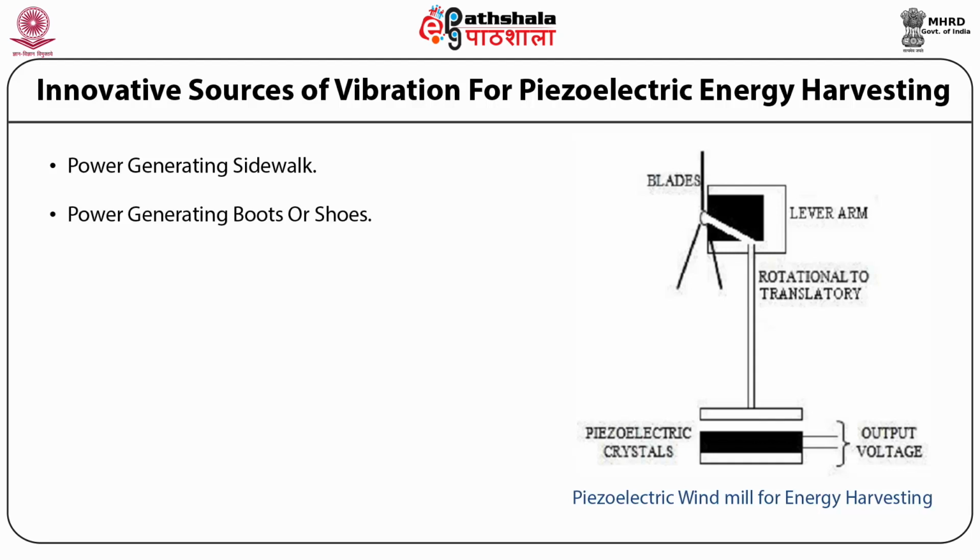Second is power generation by boots or shoes. The US Defense Advanced Research Projects Agency, DARPA, initiated an innovative project on energy harvesting which attempts to power battlefield equipment by piezoelectric generators in soldiers' boots. However, these energy harvesting sources have an impact on the body. DARPA's effort to harness 1 to 2 watts from continuous shoe impact while walking was abandoned due to the discomfort from the additional energy expended by a person wearing the shoes.